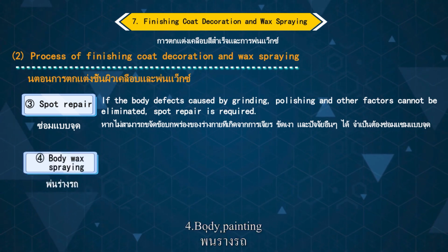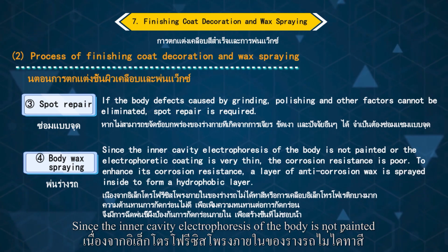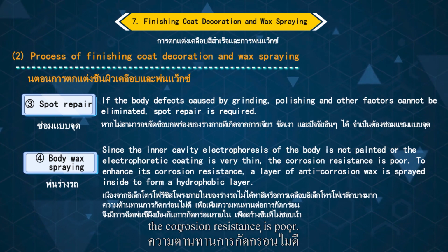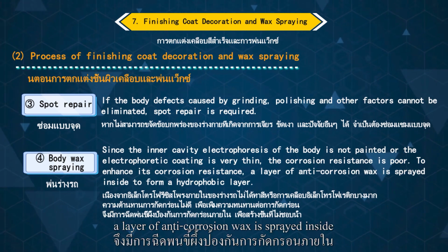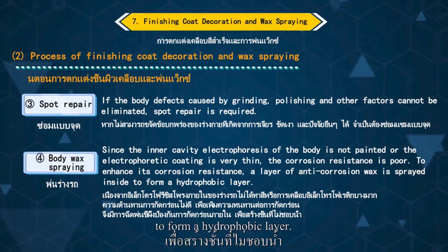4. Body painting. Since the inner cavity electrophoresis of the body is not painted or the electrophoretic coating is very thin, the corrosion resistance is poor. To enhance its corrosion resistance, a layer of anti-corrosion wax is sprayed inside to form a hydrophobic layer.